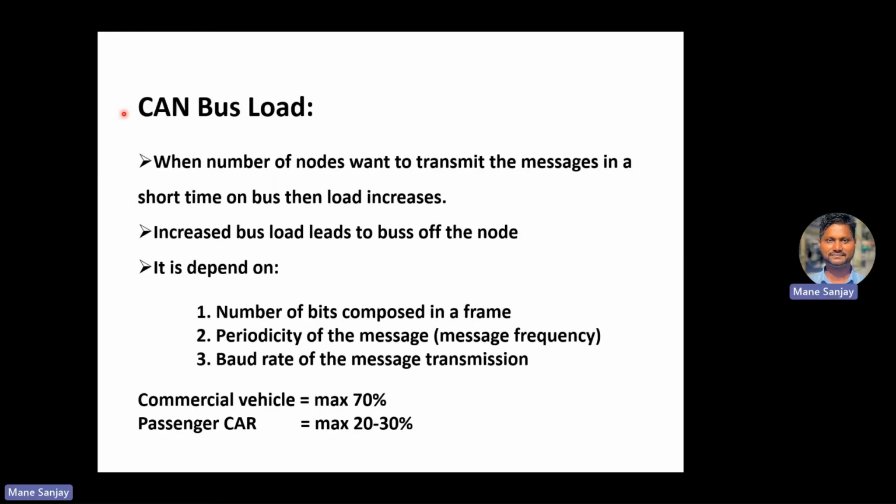But what is the role of bus load? When I say bus load, what is bus load basically? And it's very simple to calculate the bus load also. It is purely dependent on the number of messages, baud rate, your oscillating frequency, and everything matters, the standard frame, the CAN frame. So I'll take you through one example so that you can easily understand how to calculate the bus load as well.